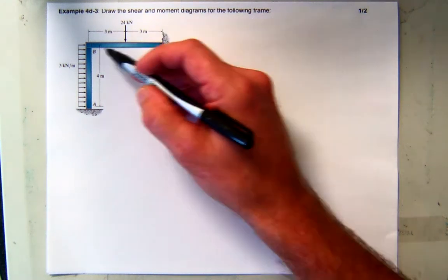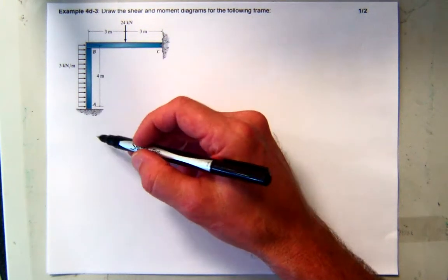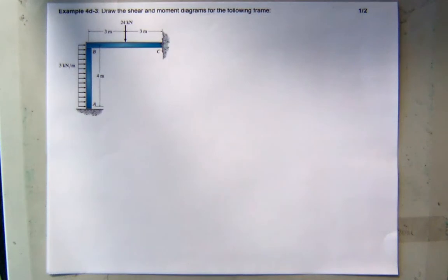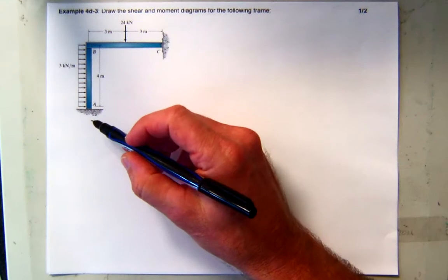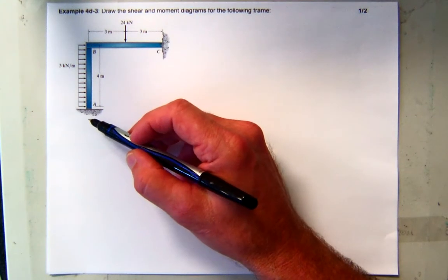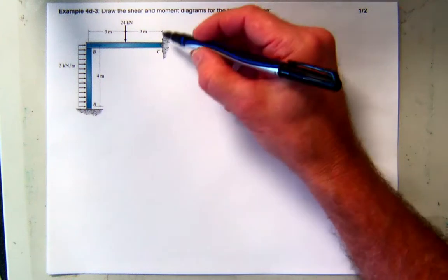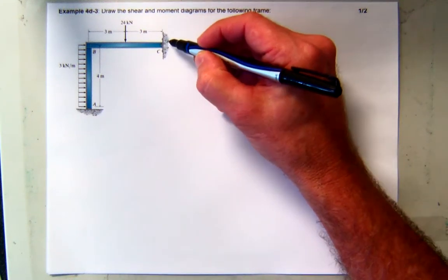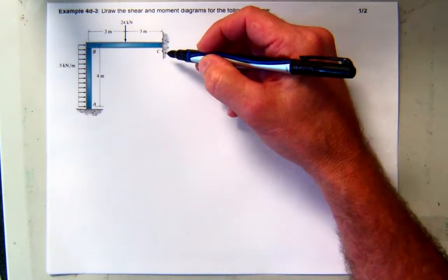So you can, again, draw a single free body for the whole structure and find your reactions. And we'll do that to get started. These will be labeled on the test, right? If it's on the exam, if it's not obvious, then I'll tell you. You might look at this and say, "Is that a fixed connection? I can't tell." So I would tell you that it's a pin.